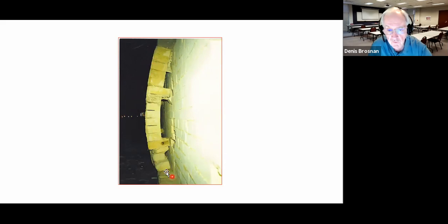And that caused the wall to bow outward from bottom to top of the kiln, where there was some expansion allowance. And in this particular case, my memory is that the expansion was so much that at one point they got where they couldn't push the kiln cars because they were locked into position by this bowing out or expansion of the wall.